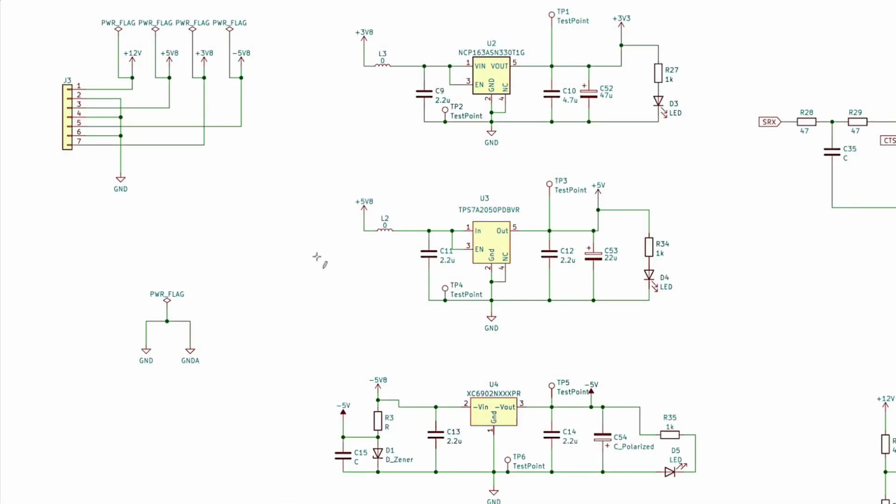I did make space for some extra inductors and capacitors around the linear regulators on the main board. I'd not put the parts in place, wasn't sure if they would even be needed. But if those very fast spikes are on the voltage rail and not just an artifact, I think putting the inductors in place would be a good idea. I will also go ahead and put all the capacitors in place.